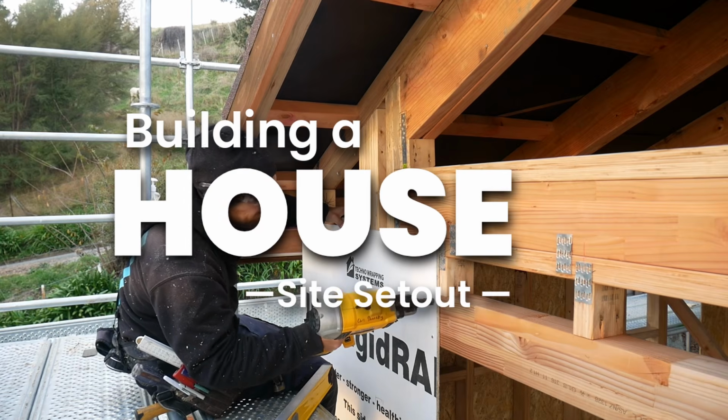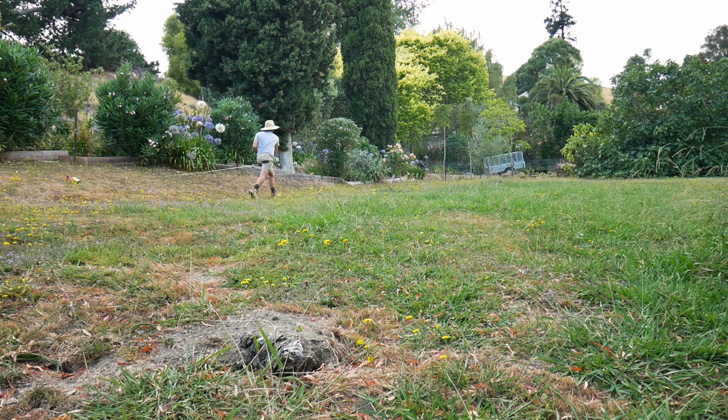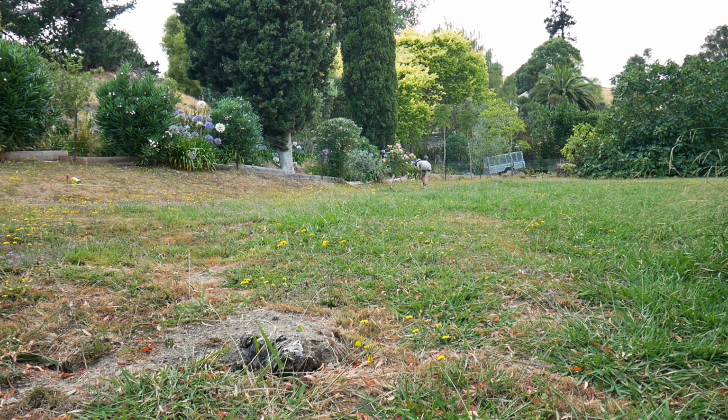This is day one, a new home on a gently sloped section, and the first step is to use the measurements on the setout plan to work out exactly where the house sits. My first two corners are located using the parallel line from the boundary and a diagonal line from the property corner.